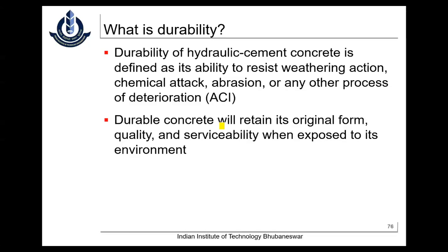At the same time, you should have periodic maintenance. If you have made a very high performance structure initially, then I'll keep quiet, the structure will take care of everything. It's not like that. It should resist, but at the same time, you should have some fund available for all these maintenances. Whenever you see some distress, immediately maintain it. Definitely, this is how you're going to increase the service life of the concrete.